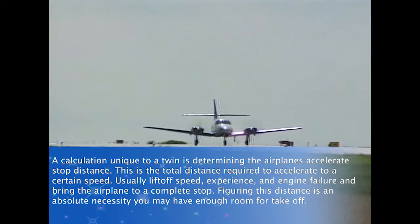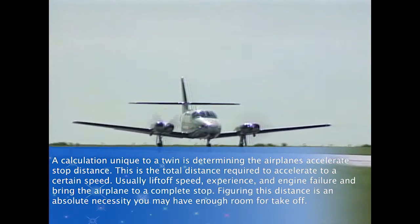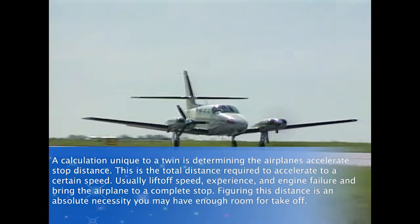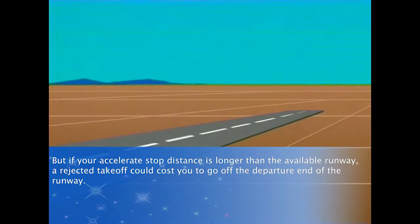This is the total distance required to accelerate to a certain speed, usually liftoff speed, experience an engine failure, and bring the airplane to a complete stop. Figuring this distance is an absolute necessity. You may have enough room for a takeoff, but if the accelerate-stop distance is longer than the available runway, a rejected takeoff could cause you to go off the departure end of the runway.